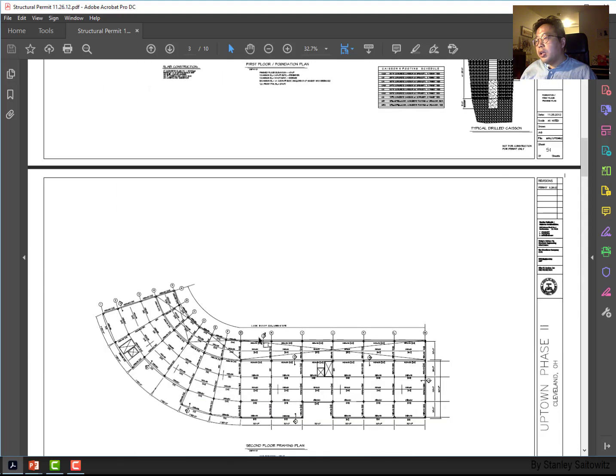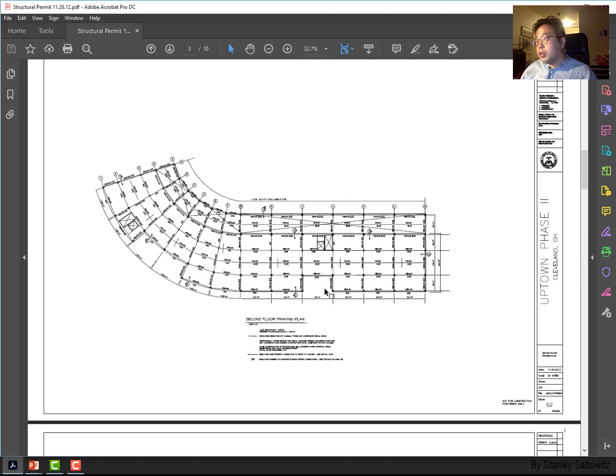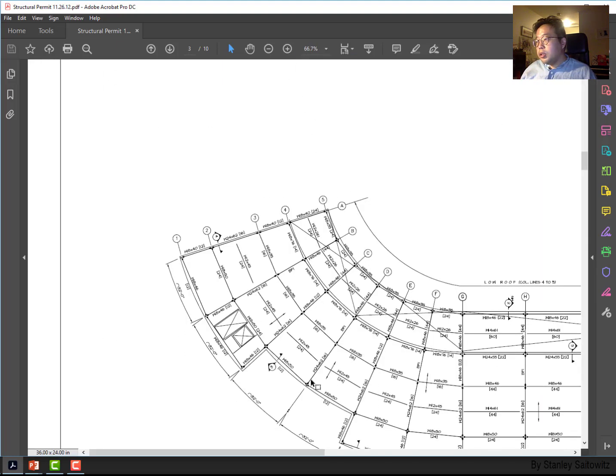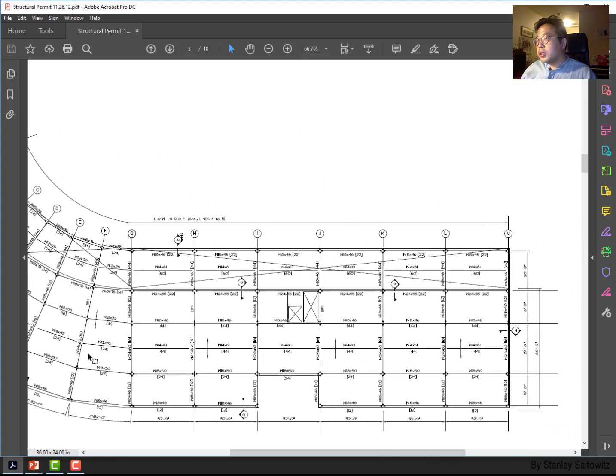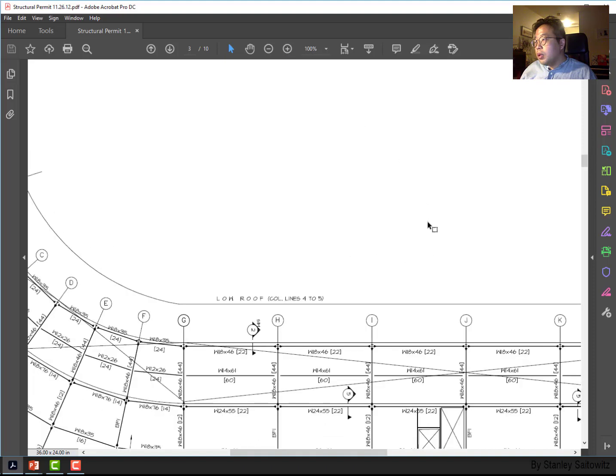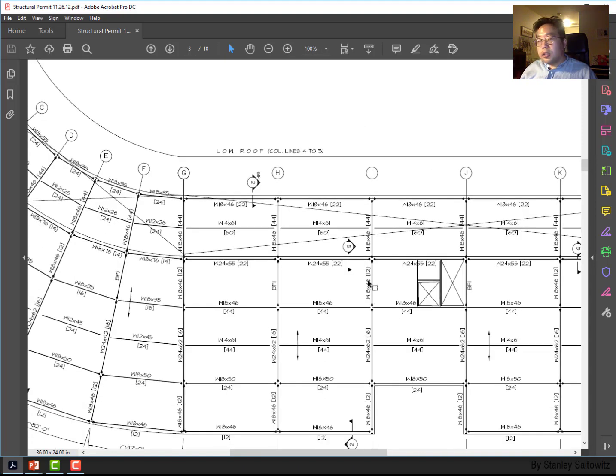Okay, and then from the top frame we talk about the steel framing here. When you see the steel framing drawing, it follows the grid system, and this grid system basically follows the column. You see the grid system here, and you can see the W series, so you remember the wide flange from the last lecture. Then you can actually find the actual number from this nominal number here.